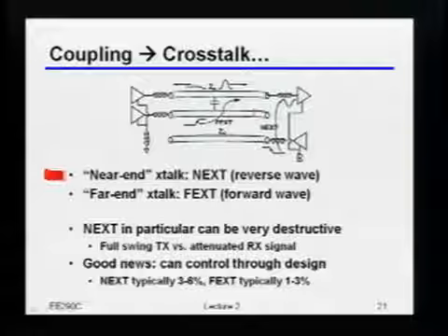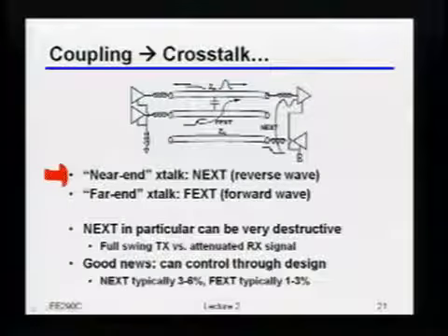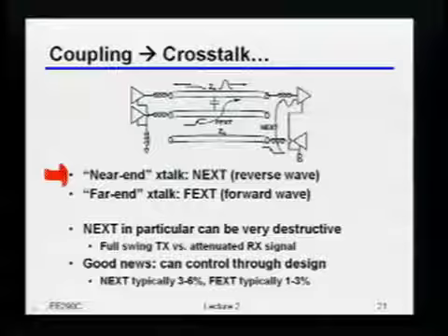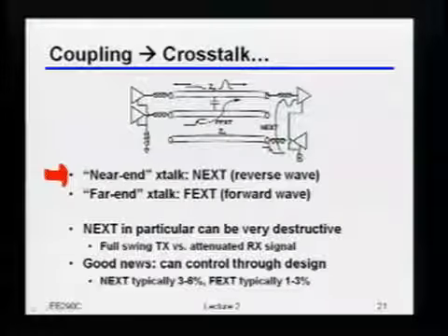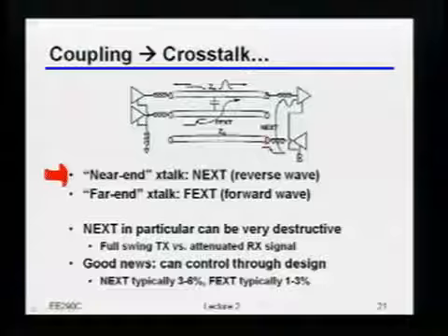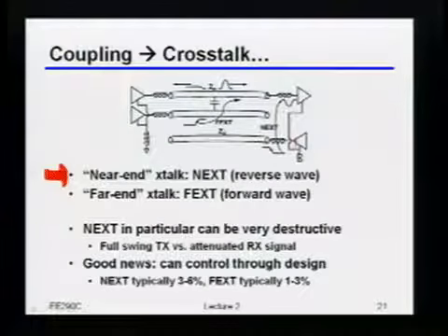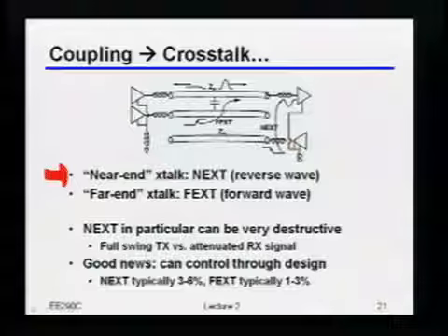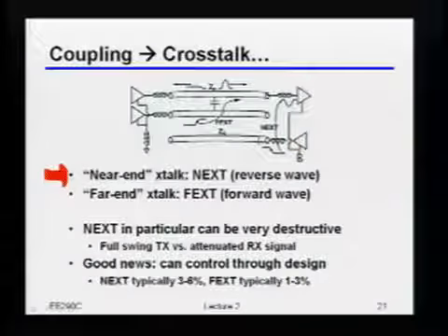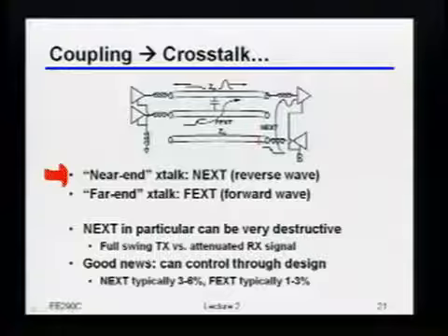The first is what's called near-end crosstalk, okay? The idea with near-end crosstalk is that, let's say I send some signal somewhere, and then all of a sudden I hit an impedance discontinuity. In particular, I could have my transmitter chip and I go out through a bond wire. That bond wire doesn't have a perfect impedance behavior. Then it hits the transmission line. I get a reflection, okay?